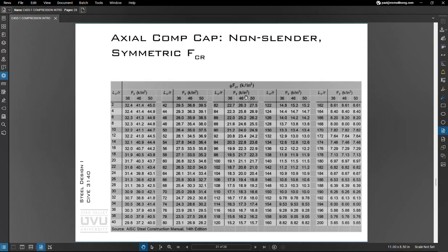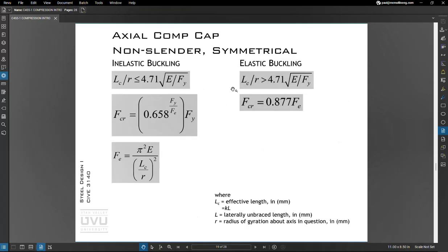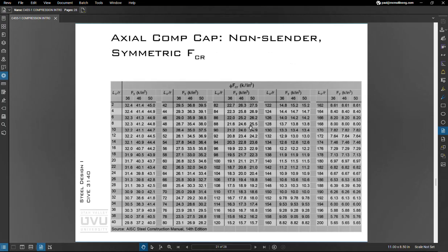Okay, this chart here on your quiz, this will help you. So one of your questions in your quiz will actually refer to this. Basically, what I can do here is find the critical buckling stress times phi. So it would be this times phi for different strengths of steel. So yield strengths, 36 would be A36, 46 is the grade B tube, and then 50 is wide flanges.